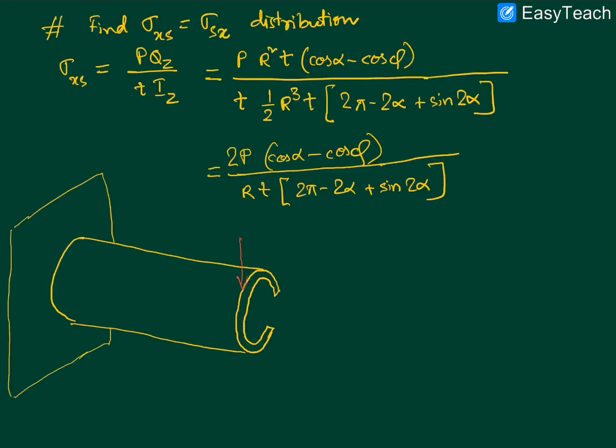So this is a very generic representation of the transverse load. We really don't know where it is, but we do understand that this is being applied through the correct location of the shear center. So if this is the line of action here, we are guaranteed to have the shear center somewhere on this line of action.